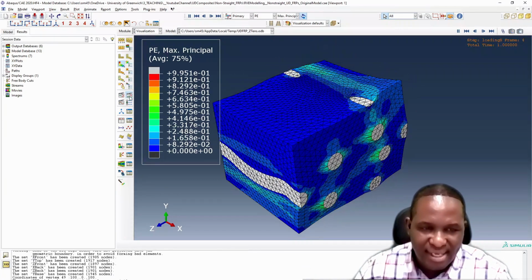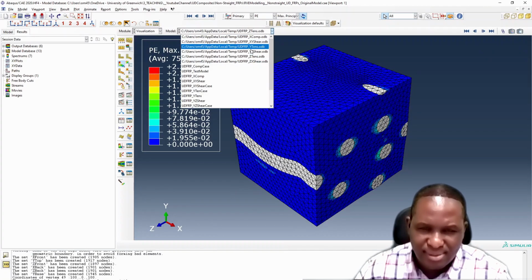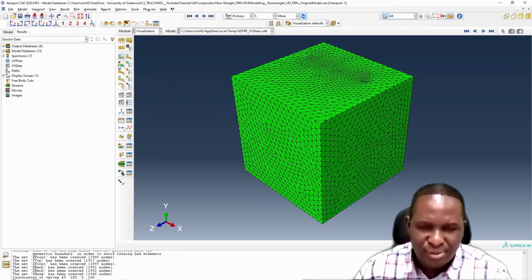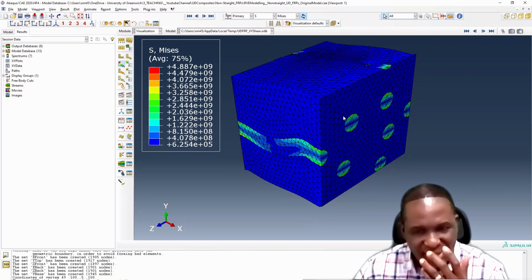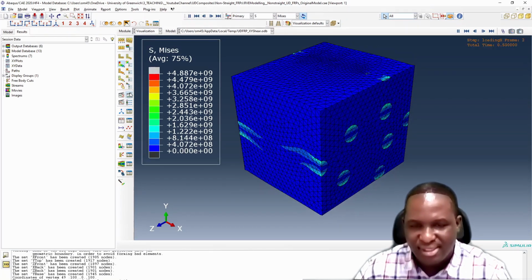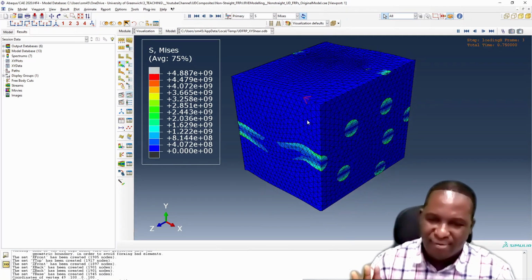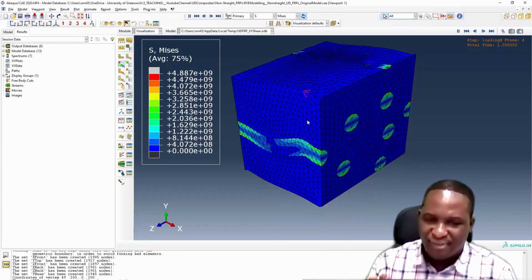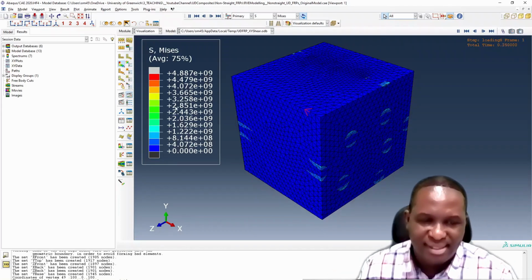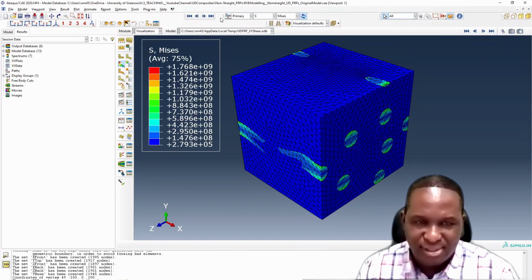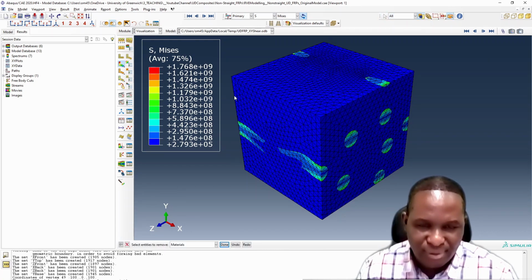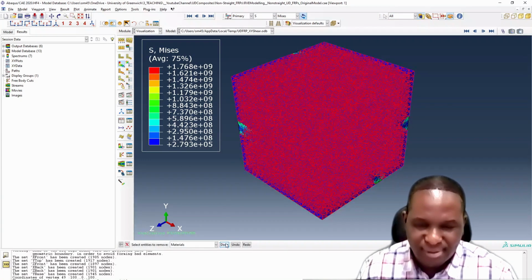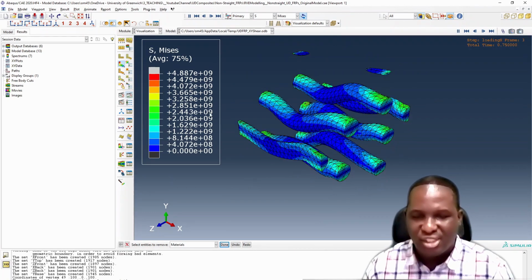So we could then look at the shear case, the XY shear. The XY shear for this system again shows some interesting results. You end up having this face being sheared and the fiber is basically being bent around. So what I'm going to do is review what actually is going on with the fiber, because it makes sense when you do a shear to see.